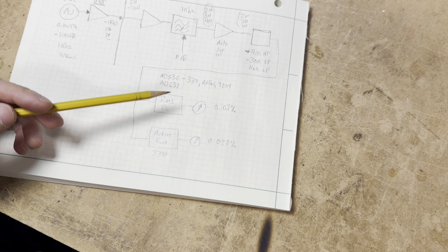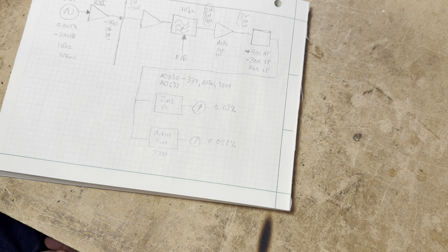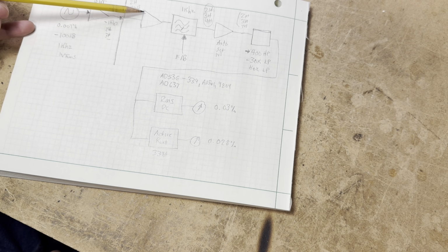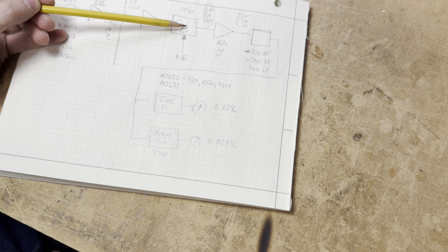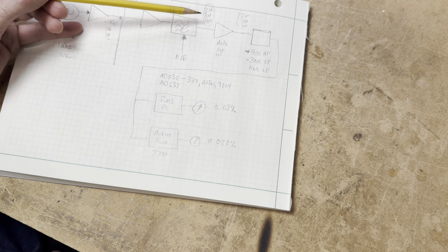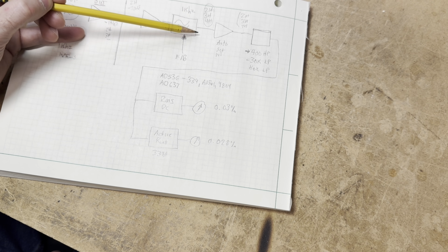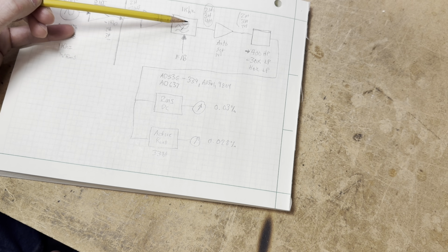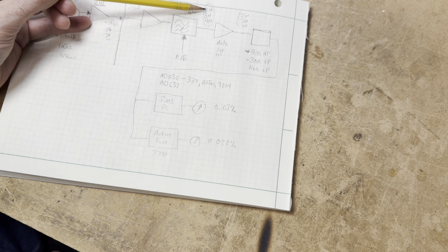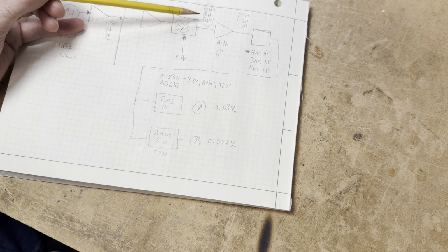So here we go. We've essentially built on paper a complete distortion analyzer system from our test signal through our device under test. We've got an input system to adjust our input signal level to a level that the analyzer can use. Then we notch out our fundamental test signal. We have our harmonic content coming out of our notch filter, which is tightened by the use of feedback to only eliminate the fundamental and not eliminate or alter the harmonic content.